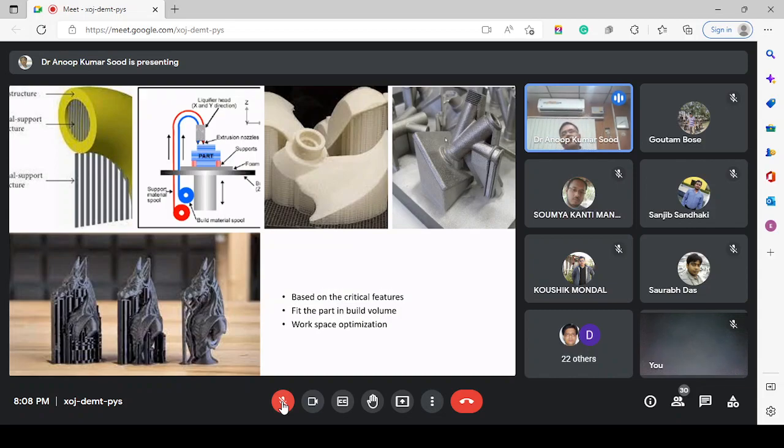But in the next part, we will discuss some of the applications of additive manufacturing at the micro level, and I will discuss predominantly two particular processes. One is stereolithography, another one is the powder bed fusion process. Now, why have I chosen these two processes? Stereolithography is commercially available to build micro size parts there. Whereas powder bed fusion is very successful in macro scale ranges, and it is widely used to build metal and alloy parts, polymer parts. Especially metal and alloy additive manufacturing is predominantly dominated by the powder bed fusion and the direct energy deposition categories of additive manufacturing.